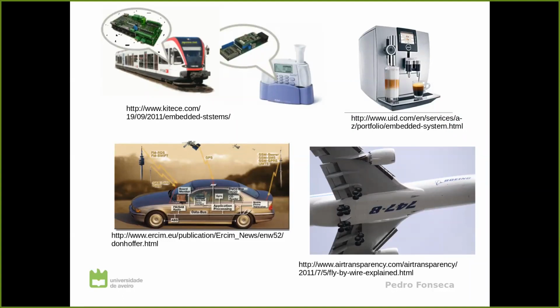When the wheels block, the brakes are attenuated or modulated by the anti-block system. Yeah, that's right. That's the point. When it detects that the wheels are blocked, the brakes are released, either totally or partially. So think about what does this mean.